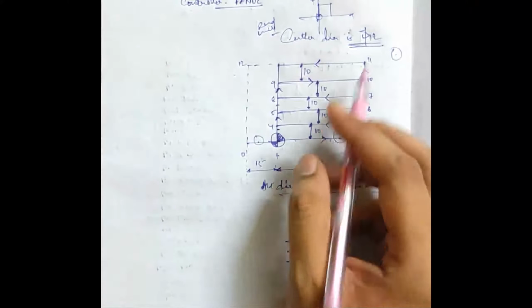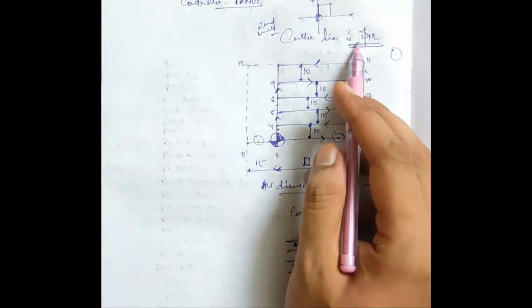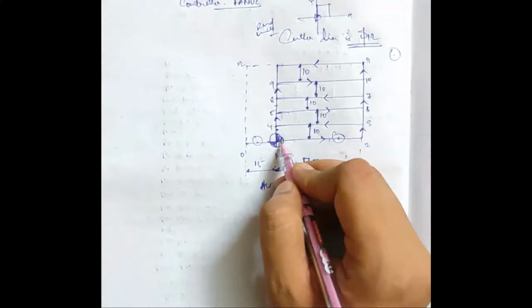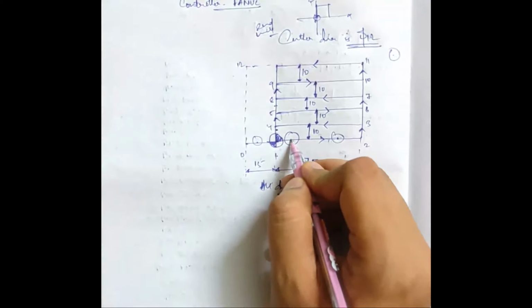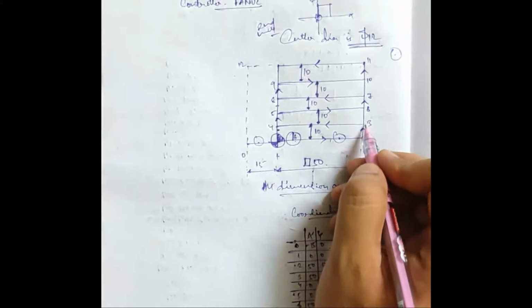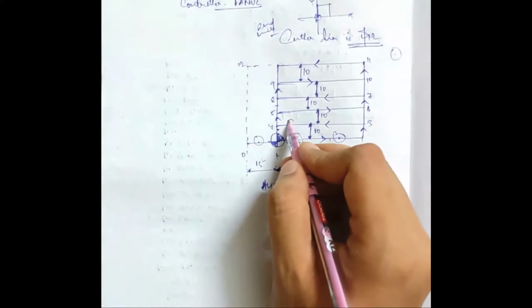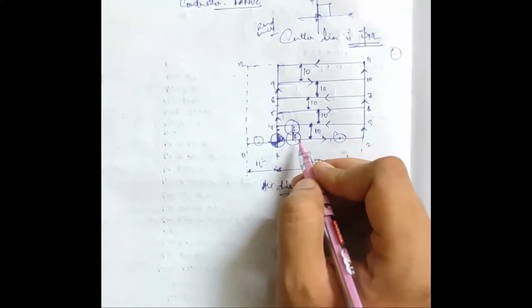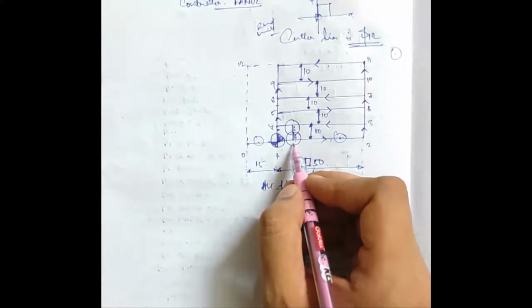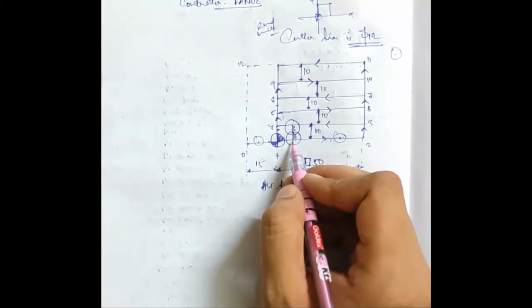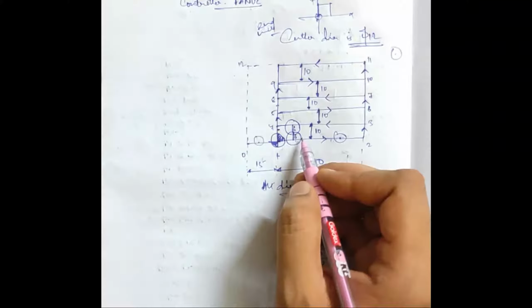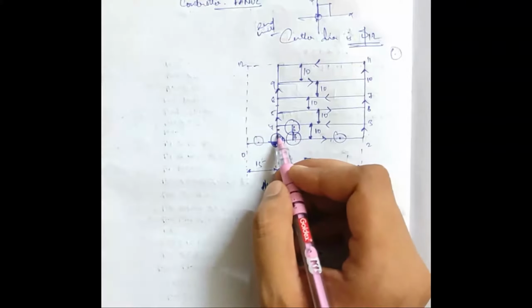While using the cutter of dia 12, it will remove metal 6 mm from here when it moves like this, and while moving from 3 to 4, it will again remove metal 6 mm from here. So the cutter path will overlap, and in this way there will be no metal left in between.